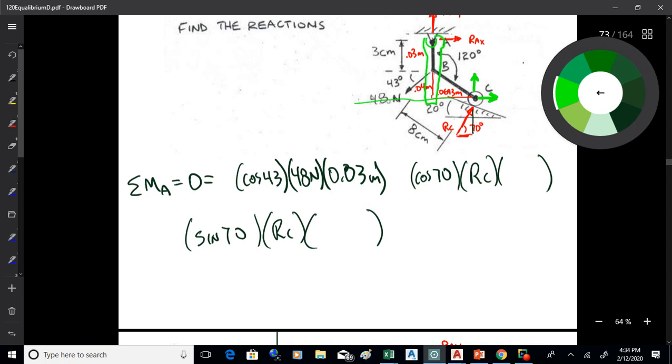Y direction. So an x force goes with a y direction. And that is 0.07 meters, I think. Now, what's the sign on that when you push on the wrench to the right and your wrench goes up to the nut up there? It's coming around counterclockwise, so that's a positive.